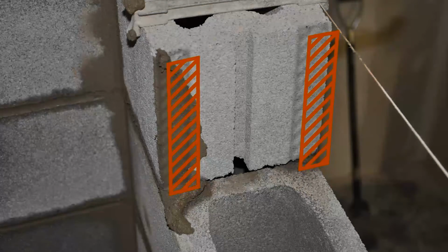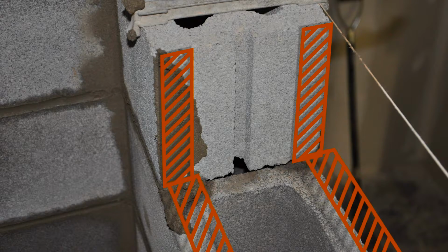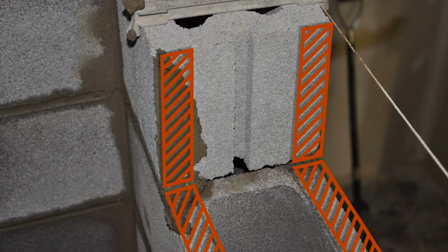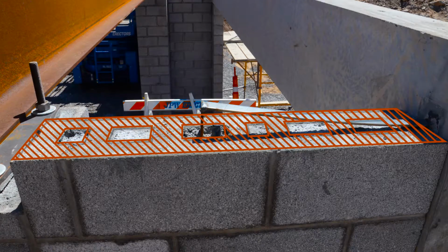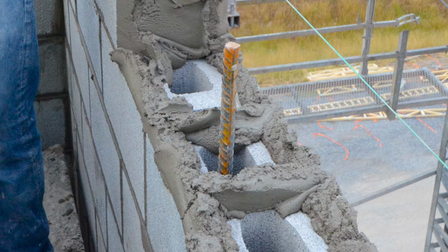A full head joint on a hollow unit covers the depth of each face shell to the width of the head joint, typically 3/8 of an inch wide, the full height of the unit. Further, all webs should be fully mortared the depth of the unit to the height of the bed joint, typically 3/8 of an inch high, in all piers, columns, and pilasters, and, when necessary, to confine grout or insulation in the vertical cores. Ensure that vertical cells to be grouted are aligned and unobstructed openings for grout are provided. Grout and reinforcing will be covered in a later learning module.